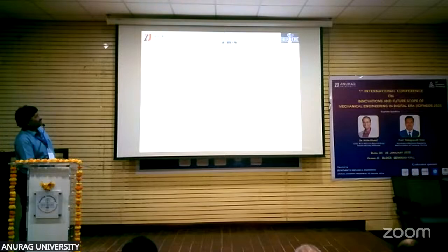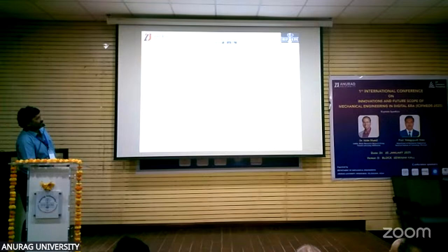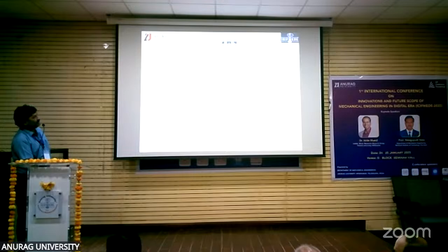Conclusions: TLBO achieved superior weld strength, 27.9 Newton per mm square, when compared with Taguchi at 22.5 Newton per mm square and GRA at 24.8 Newton per mm square. This highlights the effectiveness of TLBO for nonlinear parameter optimization. Future scope is to explore hybrid optimization techniques, extend research to different materials and welding processes, and investigate multi-objective optimization balancing weld strength, energy consumption and joint quality.